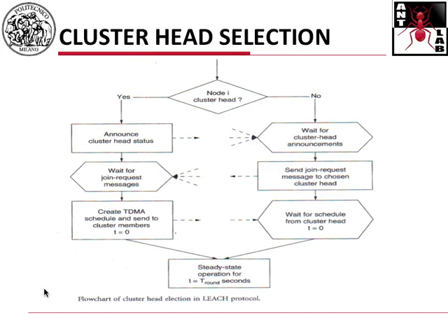So once I've made my choice, I have to send an explicit join request message back to the cluster head. Again, it's a message. Okay? And then from this point on, it depends on the specific medium access control which is put in place. If it's TDMA, I need to have feedback from my cluster head to tell me the structure of the TDMA-based approach.